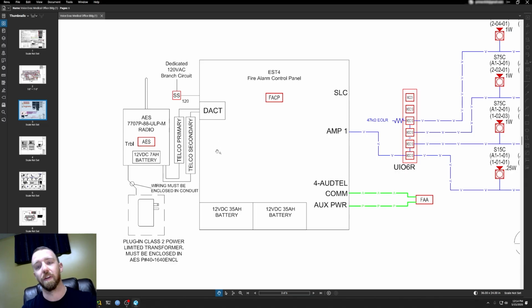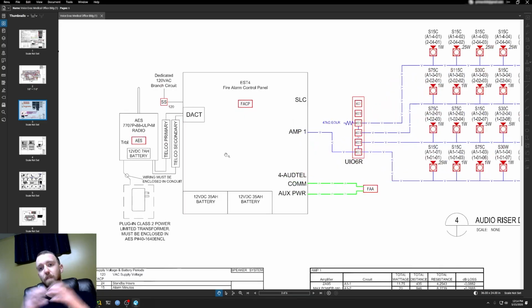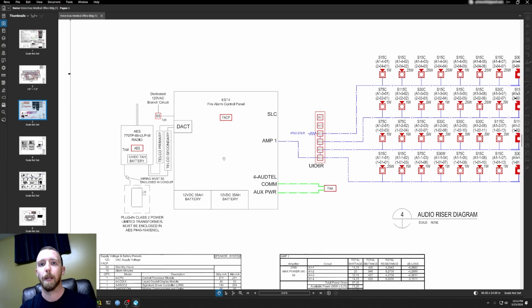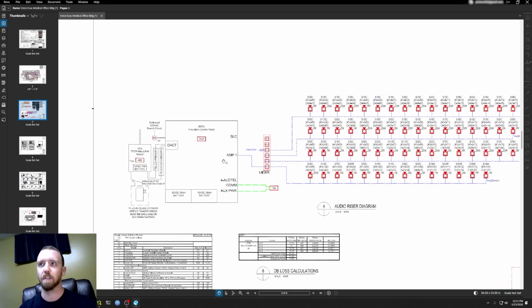Because that's another requirement of fire alarm systems, is that you don't want it just to be local, right? If an alarm is going off in the building, you want occupants to get out, but then you also want the fire department to respond in the case of a fire, right? So you need to somehow transmit that notification to the fire department, and we do that by using a radio dialer or a communicator/transmitter. So we transmit the information from the panel reading to a monitoring company, which then interfaces with dispatch of a fire department, and then you can get a responding unit on the way.